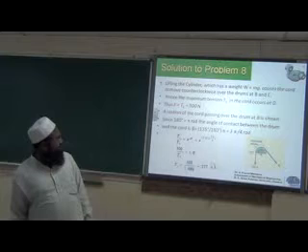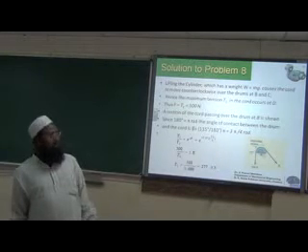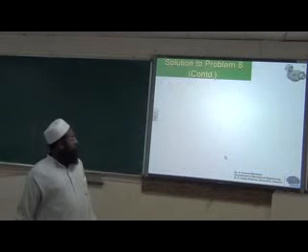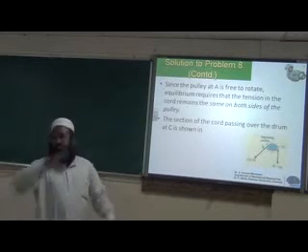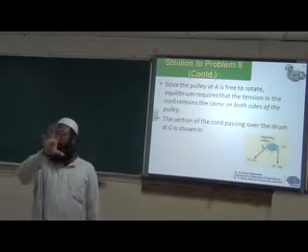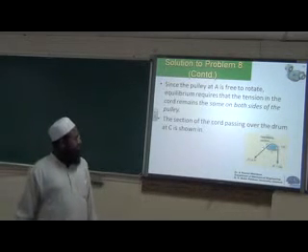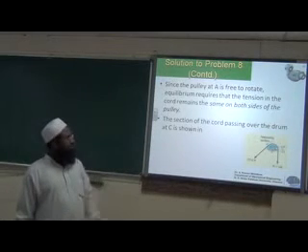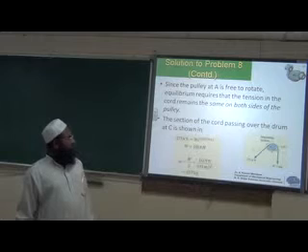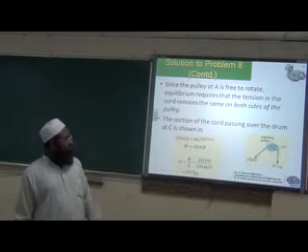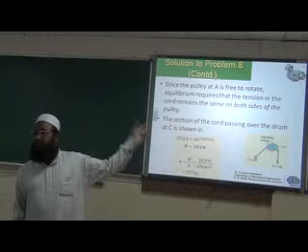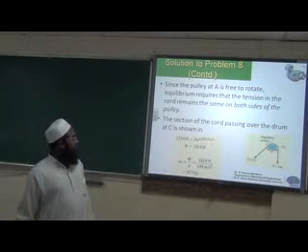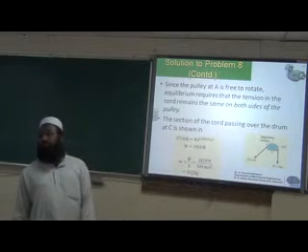Using the equation and angle, we find T2. Then consider the second drum. The middle is not important; it is an idle, free pulley. For the second drum, again the angle will be 180 minus 45, 135. Here the load is W. This is T1, which we found earlier as T2. We use the same equation, find W, and find T.